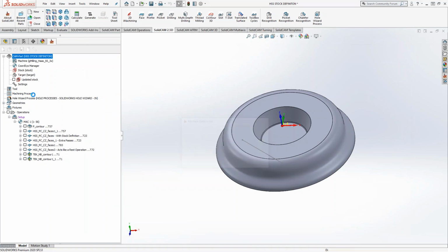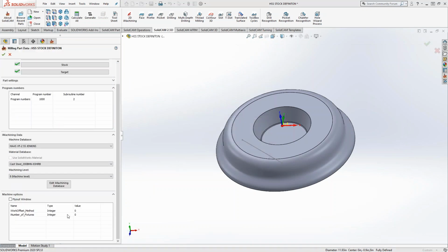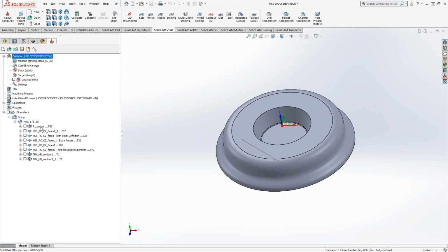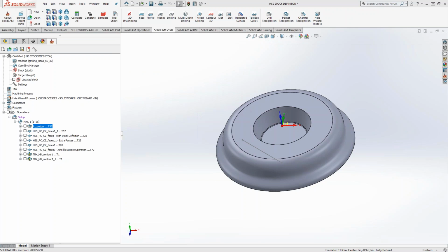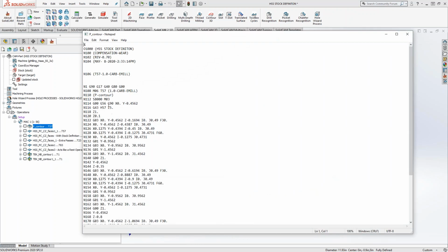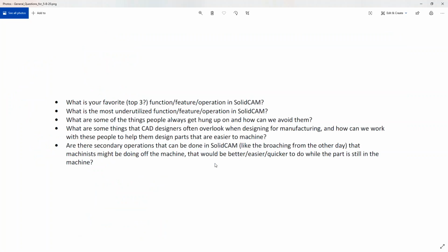In the newer posts you don't have to do this, but in the older posts you have to turn this on. For everybody in the webinar running 2018 or newer, you do have a new post. So you can see G56 is automatically produced right there. That is a big one, switching that over.